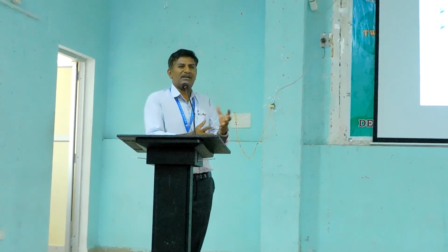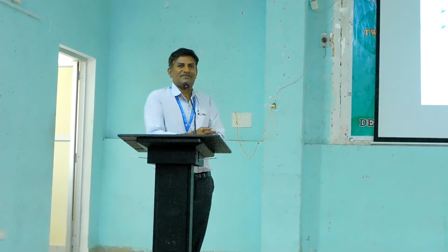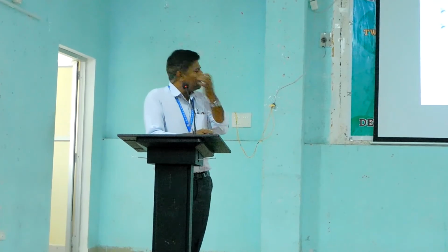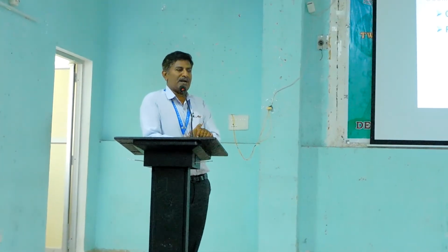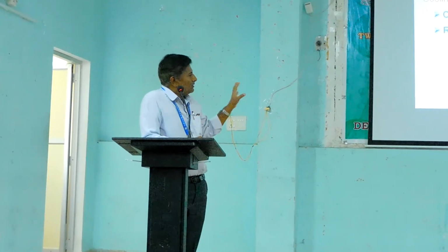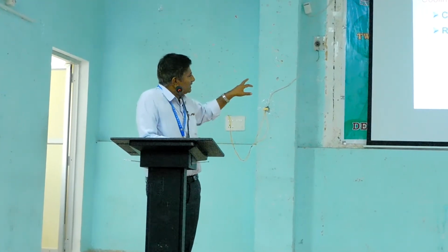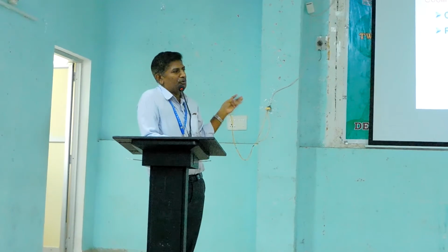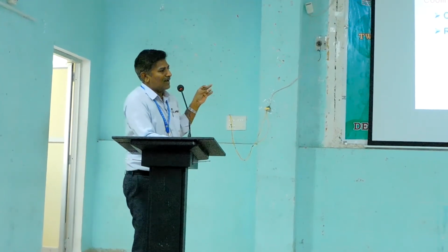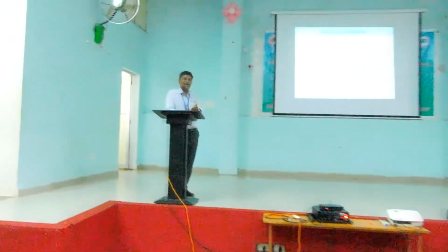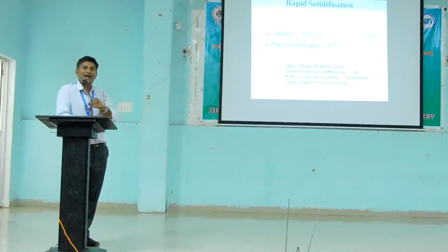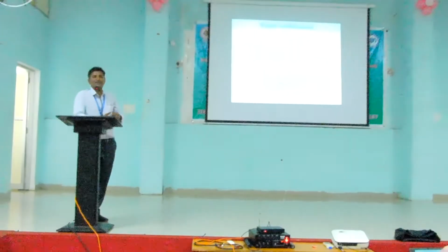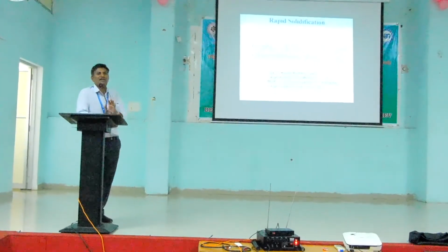Amorphous materials have a lot of advantages. As I go on presenting, I will be telling you why amorphous materials are better. To form amorphous materials, we should violate the Hume-Rothery rules. We should have large differences in atomic size. You are coming down to 1100 and change; something like 400 degrees centigrade lower. You are lowering the melting point, right? By adding just 4% of carbon.